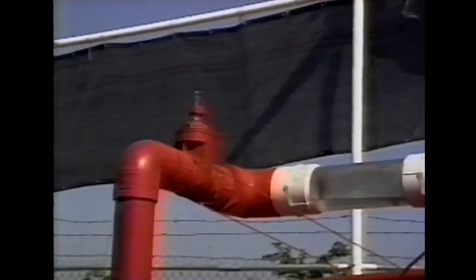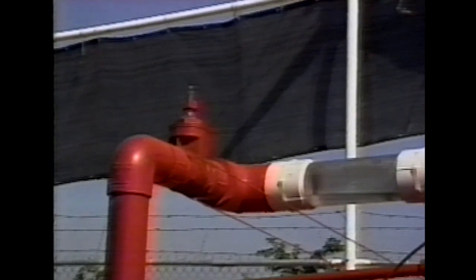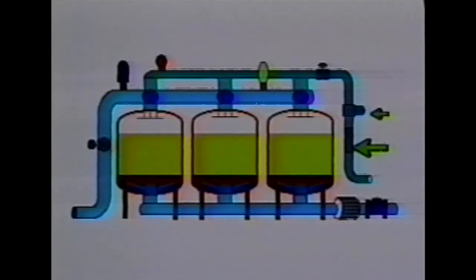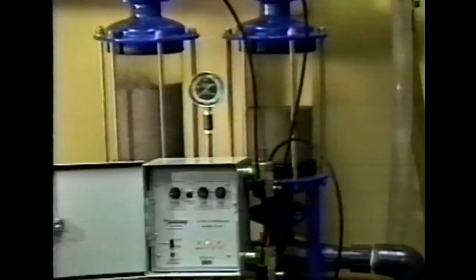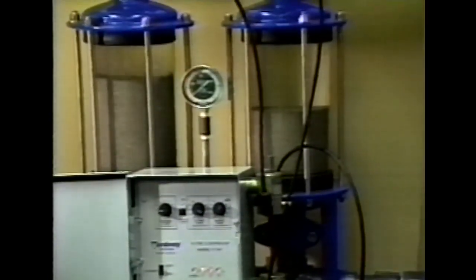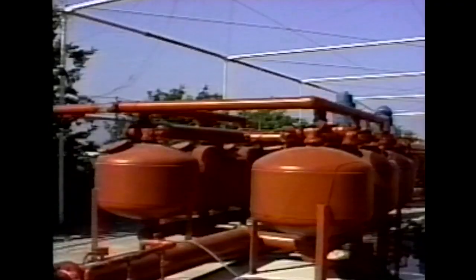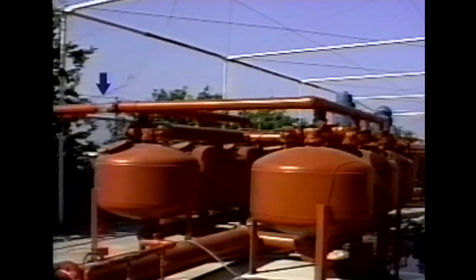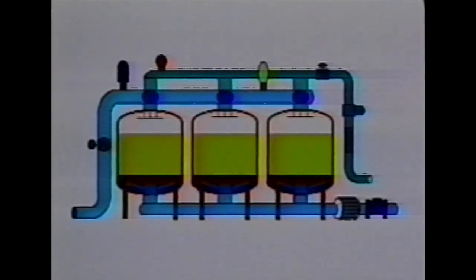This valve, then, enables the operator to adjust the backflush flow rate. Once this valve is adjusted for the proper flow rate, the handle should be removed to prevent later misadjustment. Sight glasses are used so that drip system operators can see the quality of the media tank backflush water. The backflushing should continue until the backflush water looks clean. The sight glasses must be conveniently placed and easy to see.